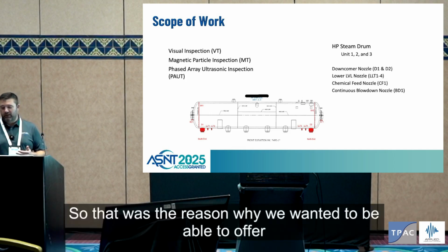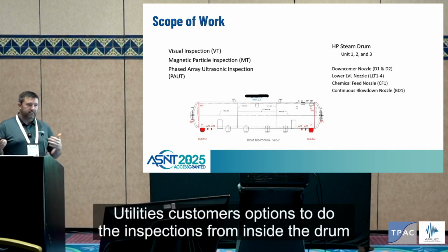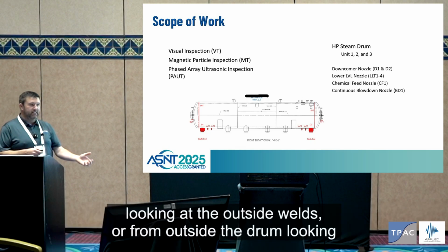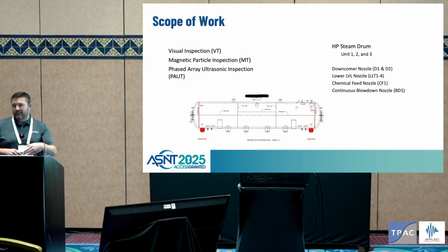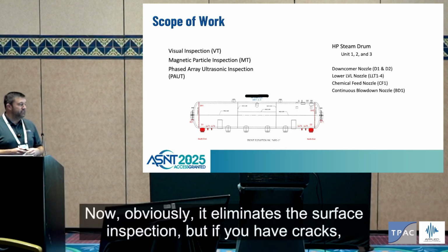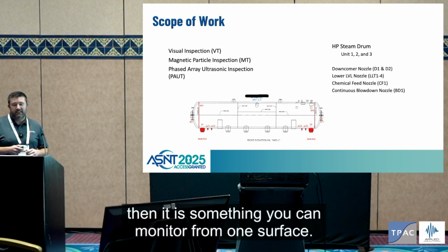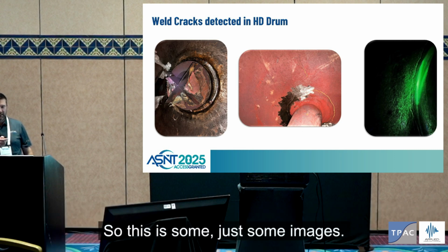We wanted to offer utilities and customers options to do the inspections from inside the drum, looking at the outside welds, or from outside the drum, looking to the inside of the welds. Now, obviously it eliminates the surface inspection, but if you have cracks, then it is something you can monitor from one surface.